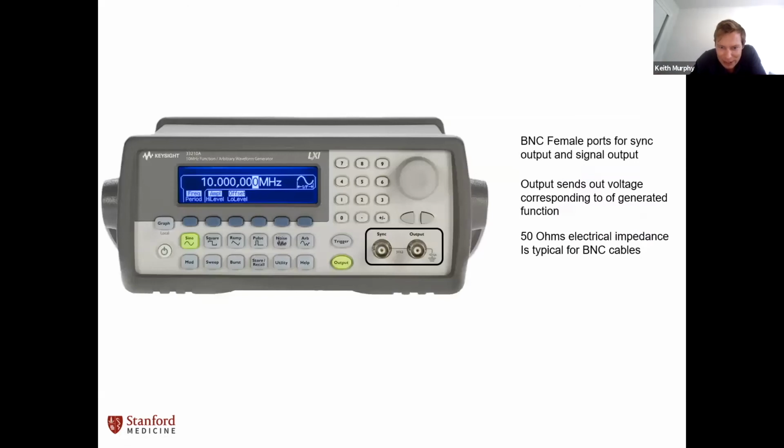Did we get through everything? Oh, let me just go really briefly into a sync and an output. The sync BNC connector here allows you to send out individual triggers. So you might send out something like a square pulse to tell other systems when your function generator starts its output. And the output BNC connector itself is very literally just carrying the function that you've told it.